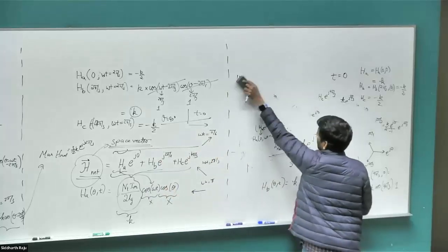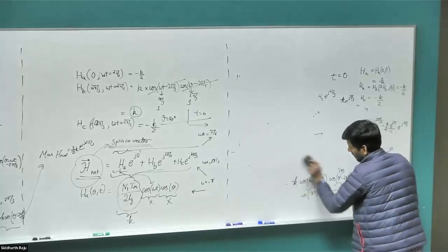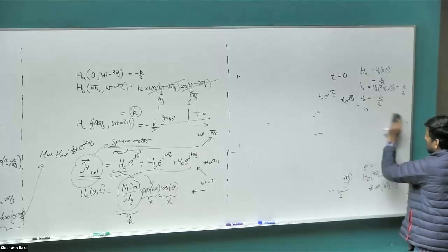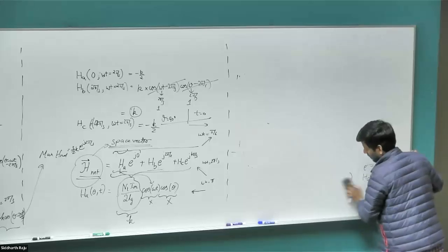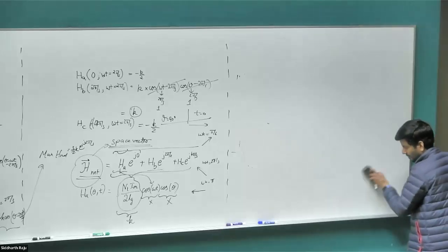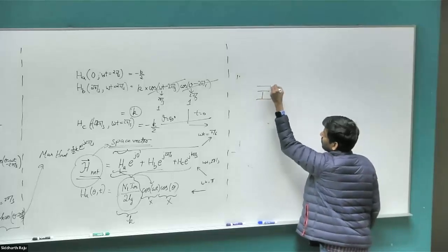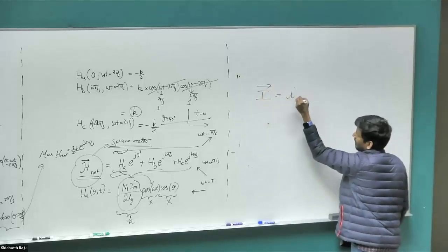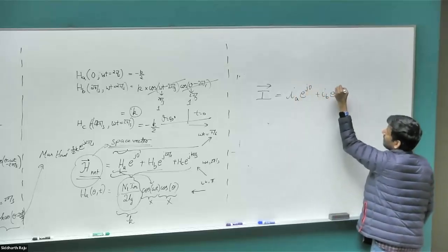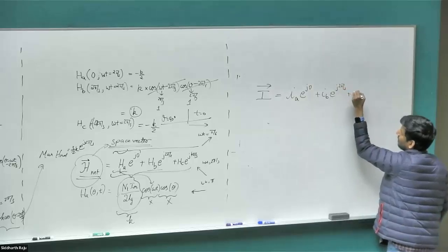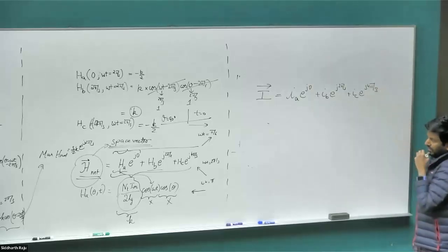So in the case of our B field, H field and all of these, that space vector has a physical meaning to it. But we are going to extrapolate this further and talk about currents and voltages as well using the space vector notation. So I'm going to declare a new term, the current space vector: IA e power j0 plus IB e power j2 pi by 3 plus IC e power j4 pi by 3.